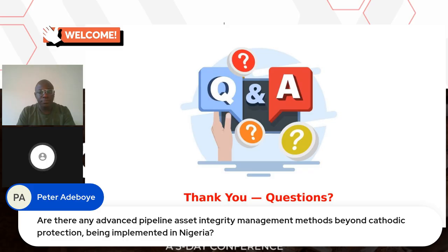I think where the gap is currently is how effectively we implement. Now there are different issues generally that happen that reduce the operator's ability to implement, from community challenges and the likes. Cost is also one of those issues. But I think technology coming in now is helping a lot. For example, one of the systems which we also implement is the internal corrosion management system, where we are tracking chemical injections with the effectiveness of what's been injected. Right, so we're tracking internal corrosion rates compared to the chemical you're injecting, so you can know if you should inject more or inject less.